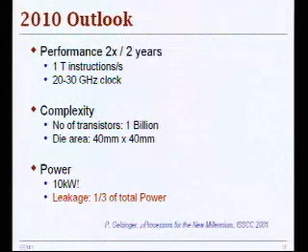And another problem that we'll talk more about later in the class will be the increasing importance of leakage power, because that power depends on the threshold voltage in an exponential fashion. So if you keep scaling your threshold voltages aggressively, then you have an exponential problem in leakage power. So clearly, these power levels seem a little bit unrealistic, as someone has pointed out last time, and we will have to find alternative solutions that will enable us to sustain this complexity growth.